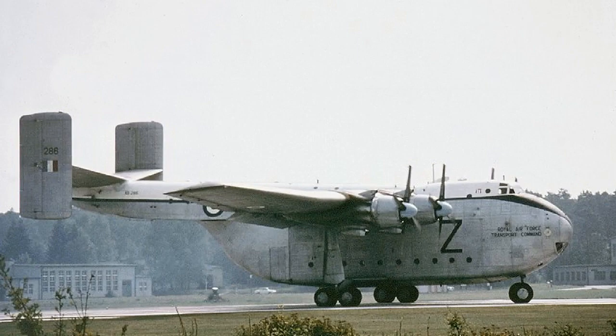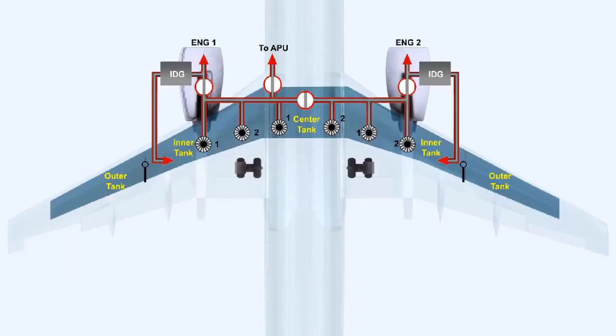While earlier aircraft used the piston engine to drive their auxiliary power units, it soon became obvious that the gas turbine engine was safer, lighter, quieter, and more reliable. The gas turbine engine auxiliary power unit uses AVTUR, which is the same fuel as the main engines use, so the problem of fuel storage and fuel management systems is minimized.